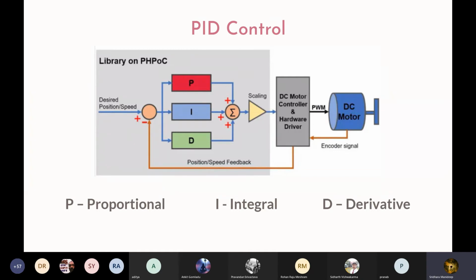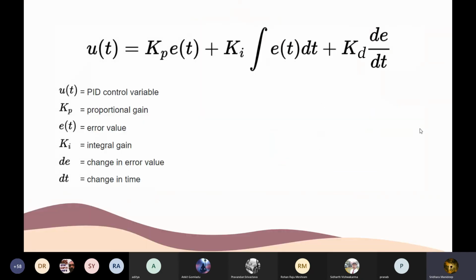So we use a derivative control as well that will stop these fluctuations. It makes the curve smooth. So this is the formula that is used in the PID control. As you can see, KP, KI and KD are the three variables, three weights that are given to each part, and we have to tune these for every individual system, so that all the variables like gear ratios and everything go into this. We calculate the voltage directly, and that voltage is fed to the L293D motor driver, which is used to set the speed of the motor.